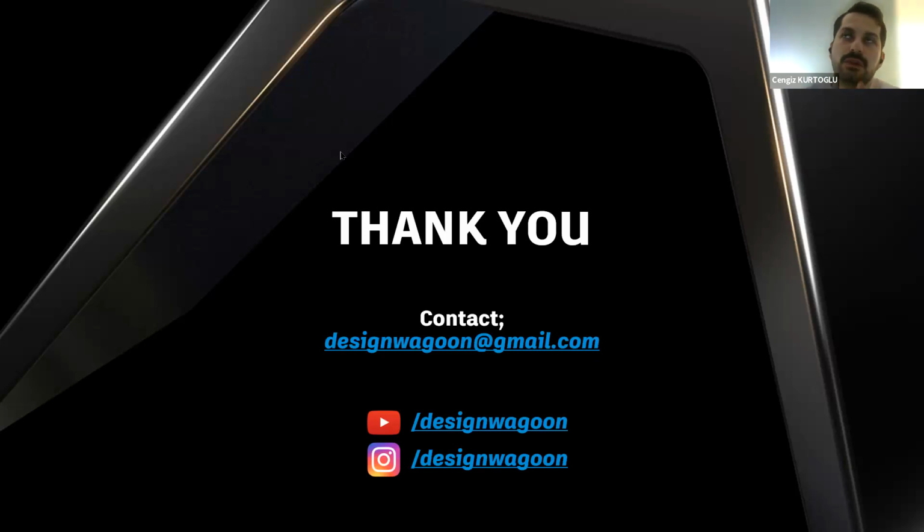For CAD modeling, to summarize for all parts and all the other projects, it's very easy to start quick projects to create a prototype using Fusion, because in the design workspace, you just need to start by creating a sketch and then switch to the 3D workspace, and you can also start to add some joints as we already did, and you can go back in your timeline to modify these parts.